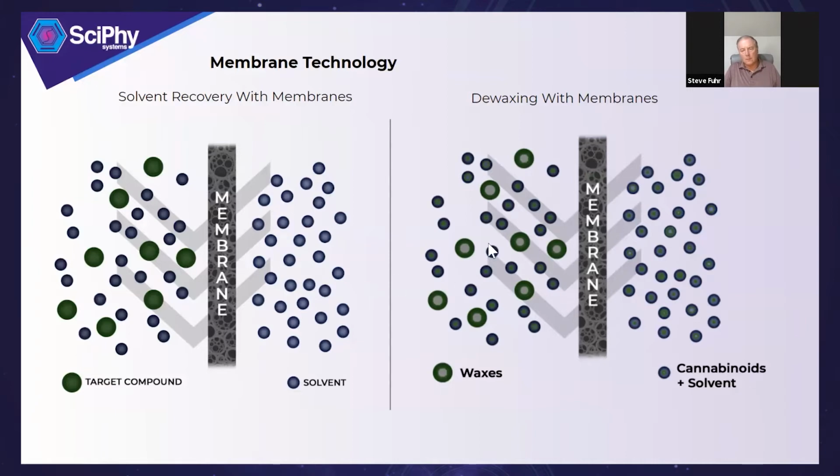So you can see here, it's a very similar process between solvent recovery and dewax, but both of them have essentially the same benefit: continuous throughput, reduced energy usage, and because of the continuous type of operation and the level of basically steady-state systems in place here, it's feasible to reduce the number of laborers, the number of technicians needed to operate the same throughput capacity of the system. So again, we're tying together all those contributing factors to this technology selection.